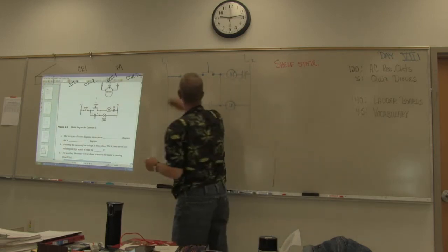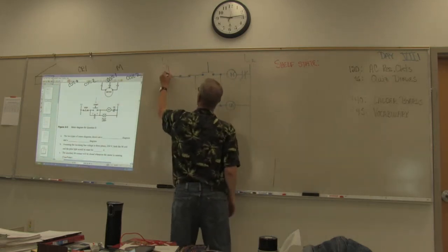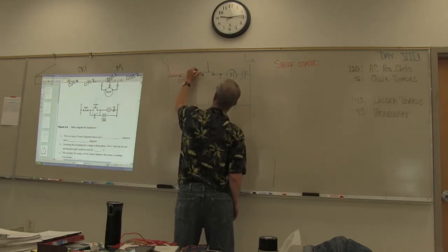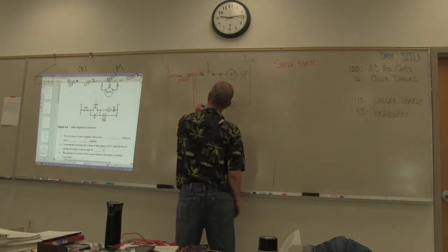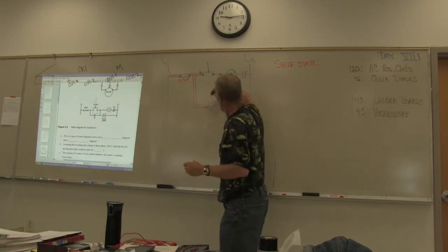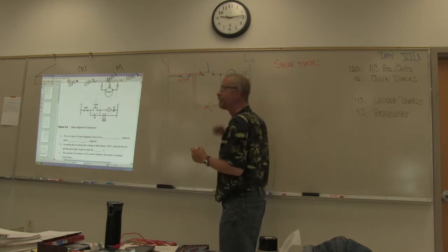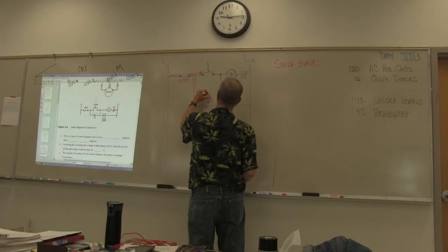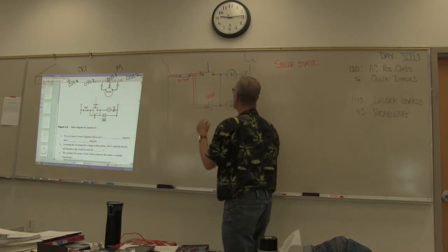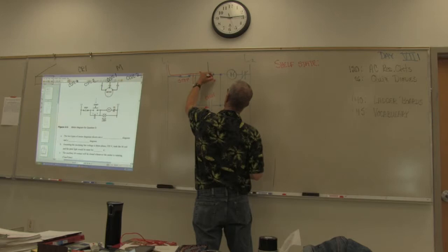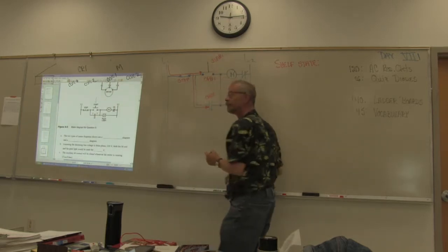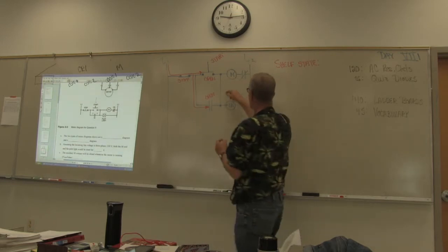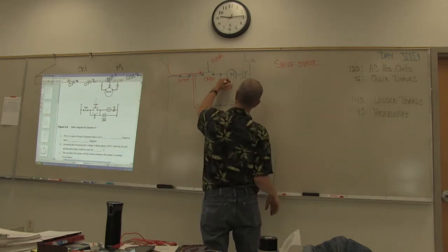Okay? Energy is going where? Across the normally closed stop, and then down, right? And right to there. Yeah. Okay, since there's no hash mark across there, that's open, right? So it can't get through. This is open, the start switch, because we haven't pressed it yet. So it can't get through, which means that you have nothing here.